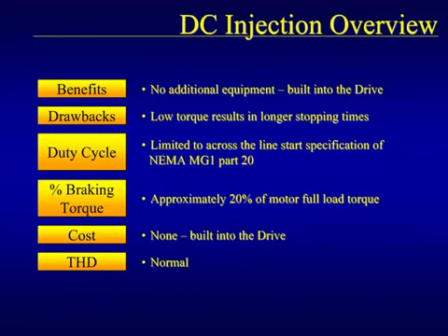However, DC injection has low braking torque compared to the other braking methods, which yields longer stopping times. Notice also that the duty cycle is dependent upon the specifications of NEMA MG1 Part 20. Motor sizing and parameter configuration determine the actual duty cycle for the DC injection function.